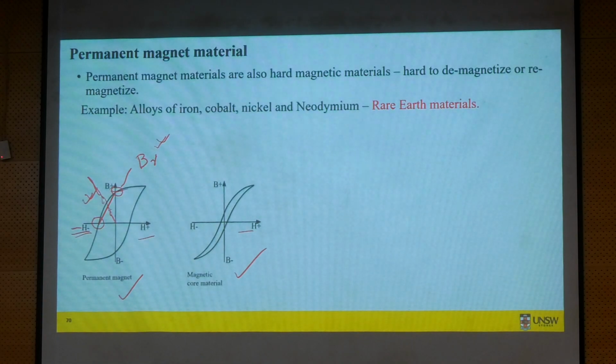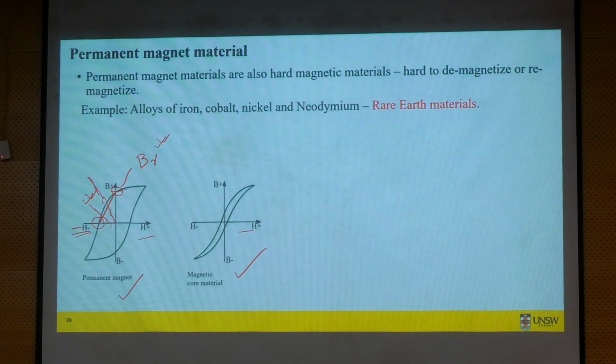If the load line is very close to, let's say, somewhere here, then you are at a high risk of demagnetization. So sometimes you may want to check, when you first start the design process, where your magnet operating point will be before you move to any design, any finite element type of work.